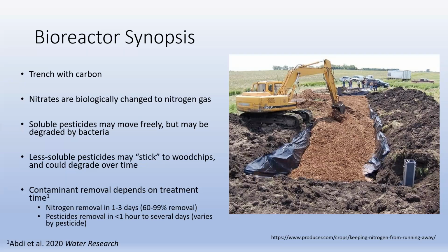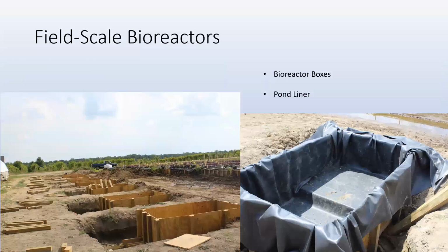Pesticides removal can be very rapid. I mean, it can be in a matter of hours to several days. And that's really going to depend on, are these pesticides going to be chewed up, degraded, decomposed by the bacteria, or are they sticking and physically stuck in the wood chips? It's going to depend, but the removal is going to depend on treatment time in a lot of ways. So that's some insights into bioreactors.